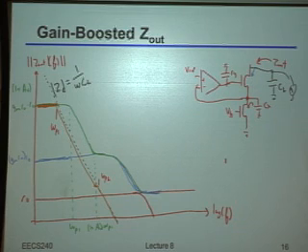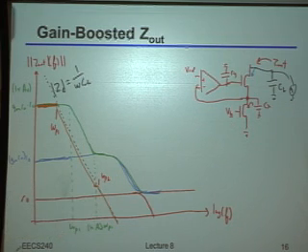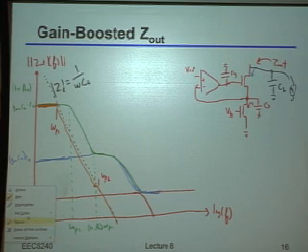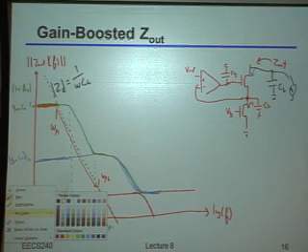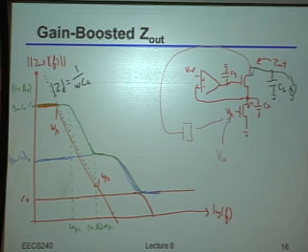The situation I'm talking about here is, let's pretend that you took this whole structure, and just as an example, let's say that I use this as an amplifier. So let me do it maybe in a different color to hopefully not cause confusion. So I'll do it in, let's try this color here. So if, for example, I drove that with a quote-unquote input signal, and I actually took this output over here, and somehow I fed it back to there. Okay, so now I've got some real feedback thing. Well, notice if I'm doing that, this is kind of my dominant pole, right? So as I change the feedback, this is the pole that I'm going to be moving around.